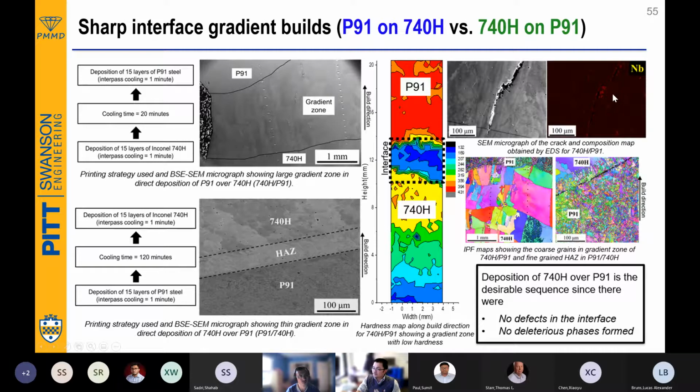You can find a lot of higher niobium concentration surrounding this cracking. And we still find this a lot, even later on when we study this kind of alloy. We find niobium carbide is probably one of the cracking sites, where you have the micro-void softening effects developed during the printing. But then, is this the whole story?